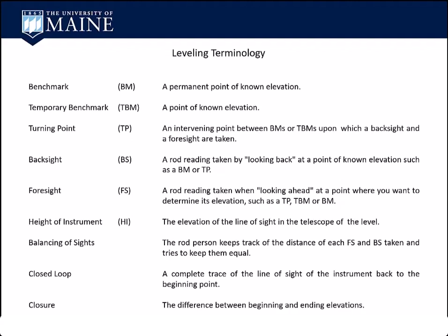So a turning point, when you run levels, these are even just points that you have to set. It's like a traverse point. It's not something that is going to last forever. In fact, these are even worse than traverse points because you're probably not going to ever revisit them, because when you run control for elevation, like traversing, a lot of it's not even on the site.